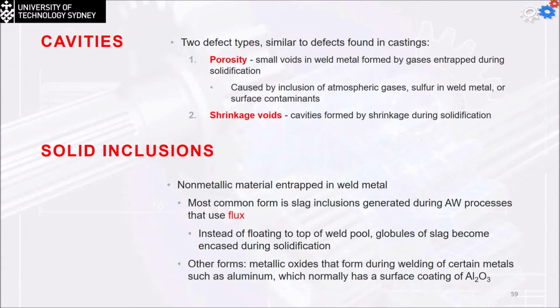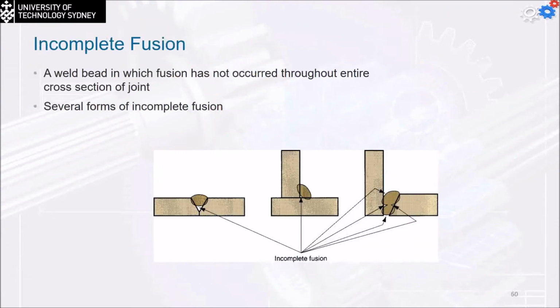The weld profiles in arc welding are as follows. Okay, now this one has three stars. This is the desired shape, the good profile. Sometimes we may have an undercut, an extra melted area, and thus we are going to have weakness here. A portion of the base metal has been melted away, which is not meant to be.